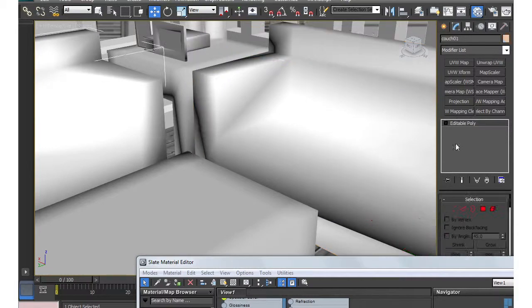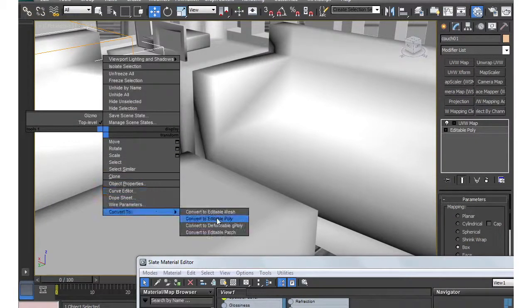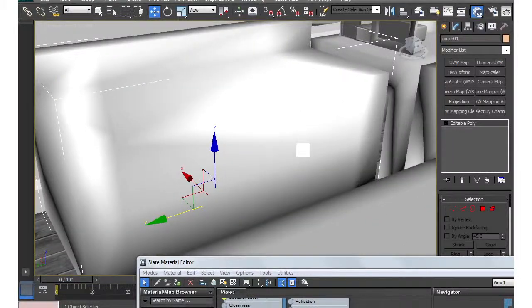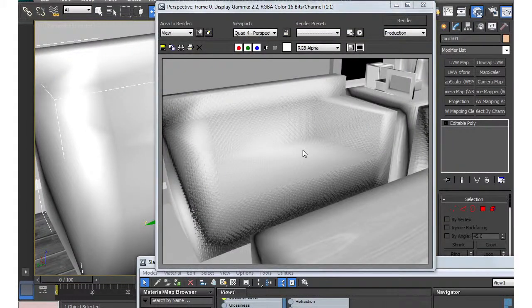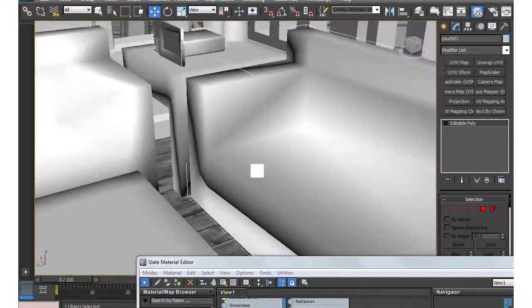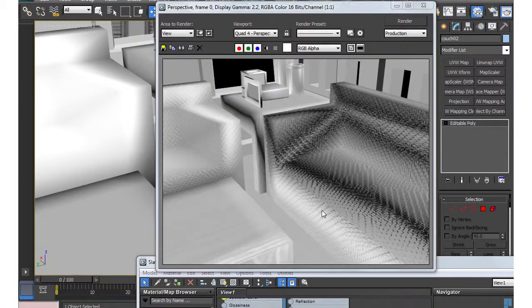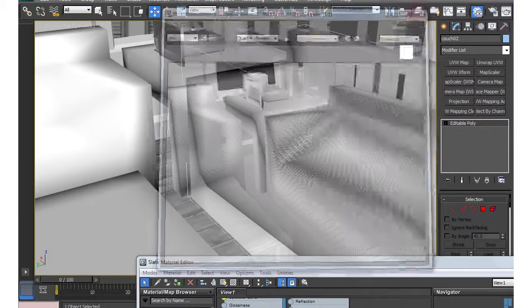Convert to Poly. This one also gets a UVW map, spherical, planar, box. Convert to Poly. Hitting spherical and planar makes the UVW map equal on all sides. Not sure I did that for the big one. UVW map, spherical, planar, box, convert to Poly, Shift Q. Pretty good.